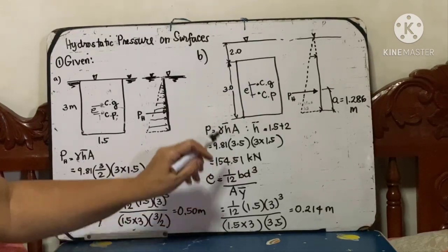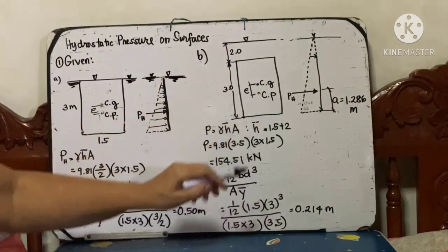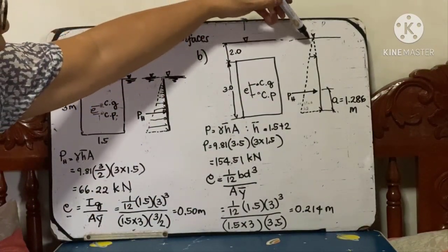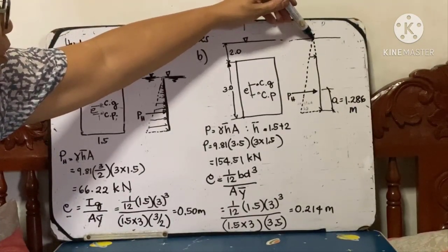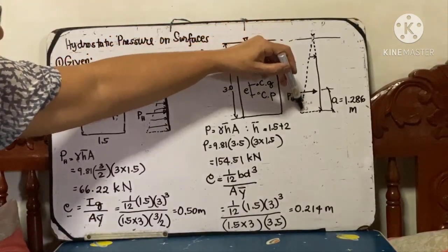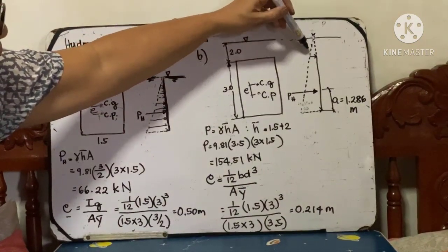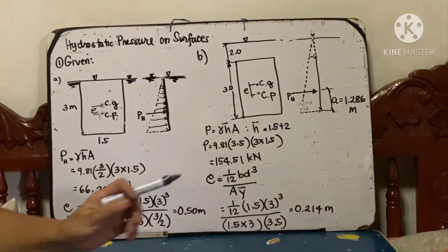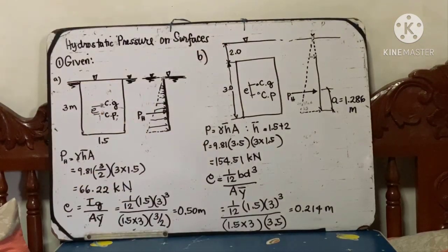And again, the CP. Where is our center of pressure now? If we draw our hydrostatic pressure diagram again, from here it is 0, because this is atmosphere. So the gauge pressure is 0, increasing gradually down to the bottom. This is the pressure diagram we can draw, but only up to here is our height. So now you have a trapezoid. Where is the centroid of the trapezoidal section?